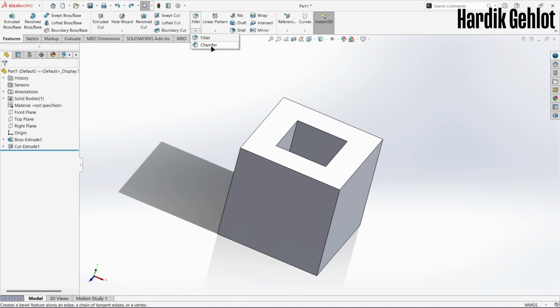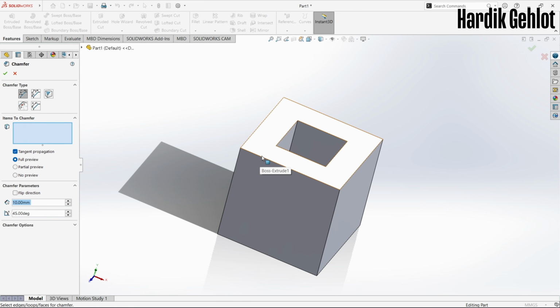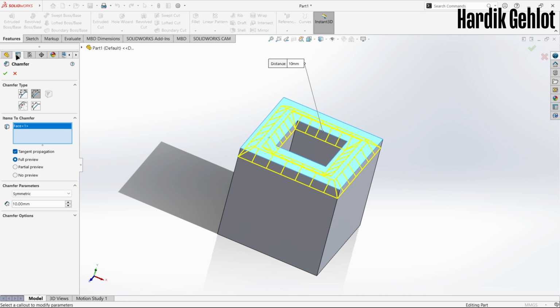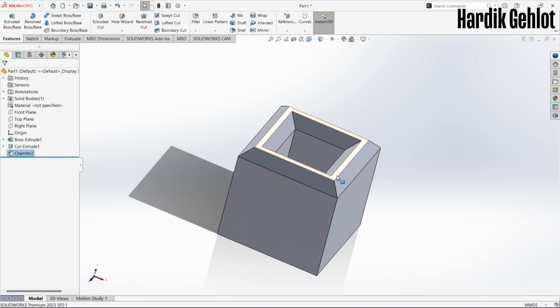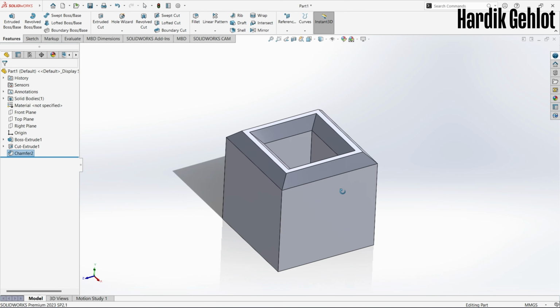Below the fillet, you will see the chamfer feature, which converts the edges into slopes. Select the edge and type angle distance, distance, vertex, offset face, or face. Similarly, you can select all the edges by selecting the plane. Mostly, angle distance and distance chamfer are used.